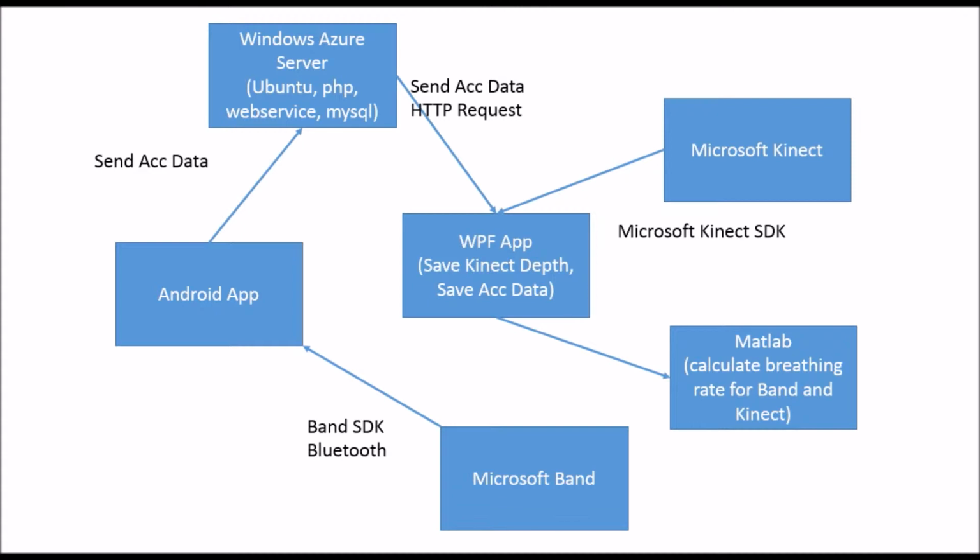Then we used the Microsoft Kinect based depth sensor to calculate the depth information of the chest. We all know whenever we breathe, the depth of our chest gets an oscillation of increasing and decreasing. We wrote a WPF app connected to the SDK to get depth information of the mid-spinal skeleton position. We saved that depth information in CSV format. We used the same MATLAB program to calculate breathing rate through the autocorrelation filter and sequence of period calculation. Finally, we compare both of the respiration rates together.